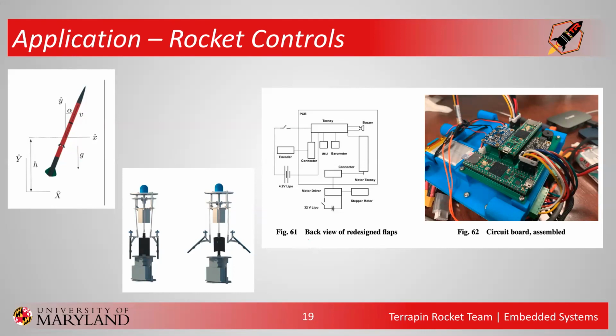So it's a very complicated system, but at a very simple level, and there's an image of it on the right, the computer that we made has those two sensors, as I said. They all feed into what we call a Teensy, which is just like a faster Arduino with more memory, but the same concept. It reads that in, tells the flaps to deploy to an angle, and brings the altitude down until it's at a good spot.